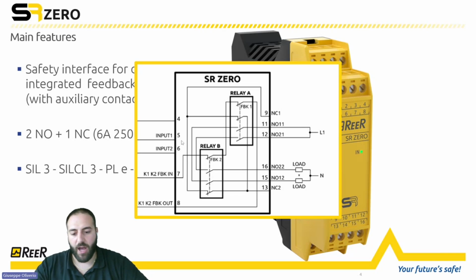On pin number 5 and 6, you have the inputs where you physically connect the OSSD output from the safety device to the safety interface. Plus, you have two normally open contacts plus one normally closed contact.